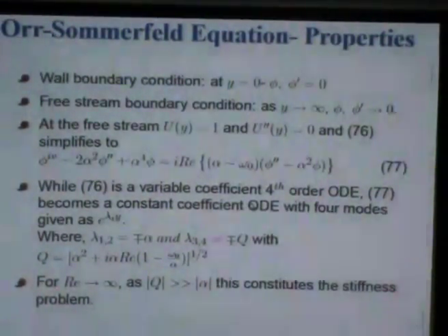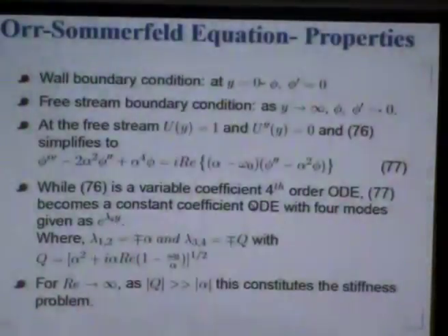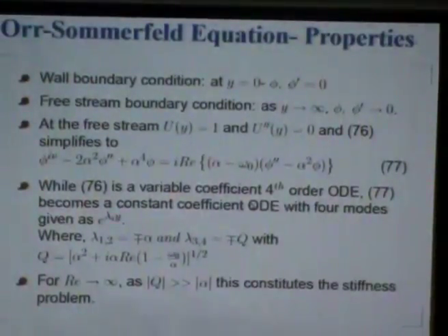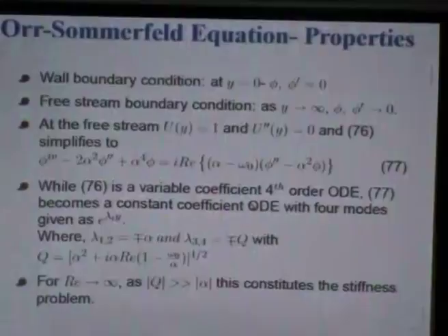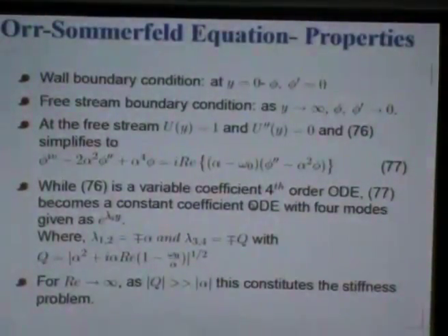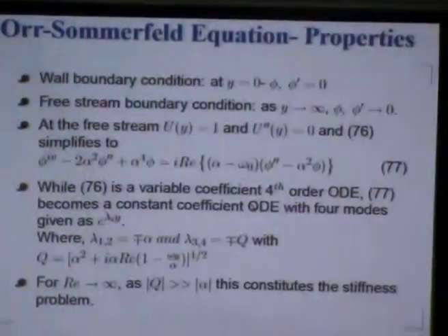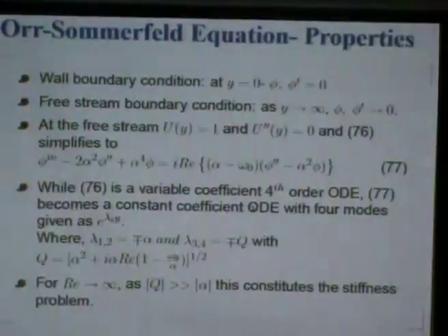That is one thing. The other thing is, most of these problems of instability arise when this parameter here, the Reynolds number, happens to take large values. You know, for flows at low Reynolds number, you do not see instability. Instability is characterized by a certain range of parameters, and in this case it so happens this Re has to be large. Well, I have just shown you a sort of estimate.